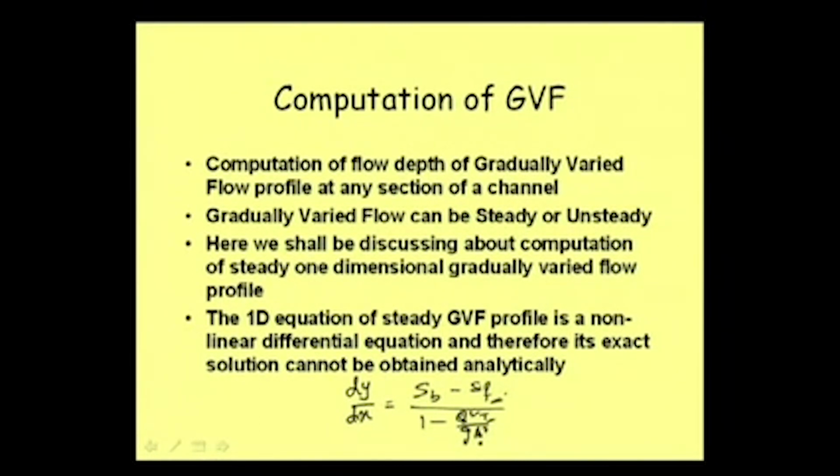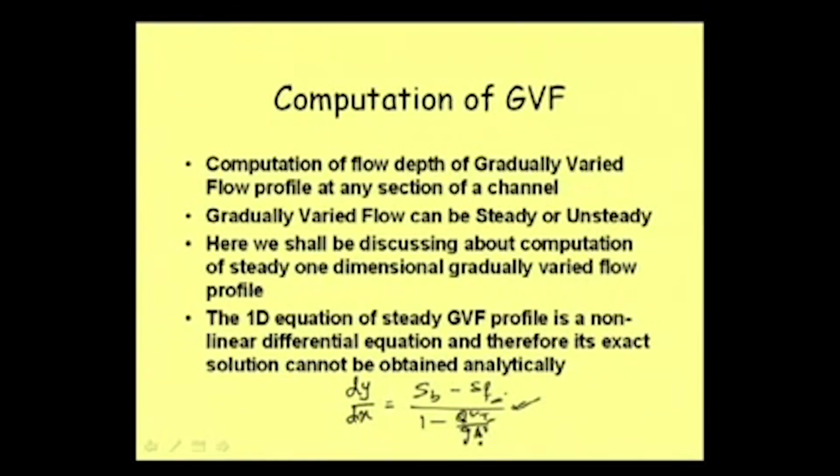If it is a non-prismatic channel, then only these things are also varying with x. If it is a prismatic channel, all these are pure functions of y. So, the right hand side of this equation is a function of y, and that is why this equation is a non-linear differential equation, and we cannot get a direct analytical solution of that.